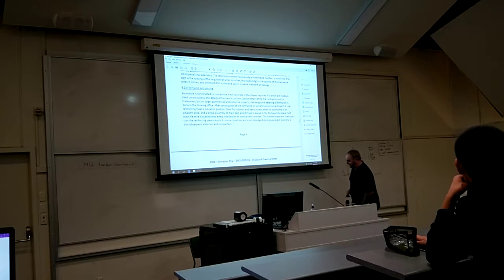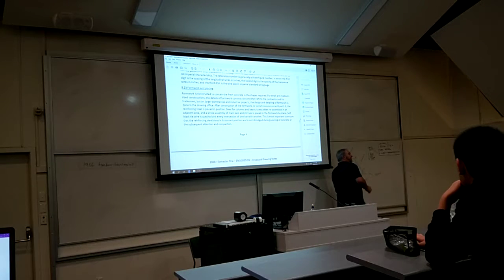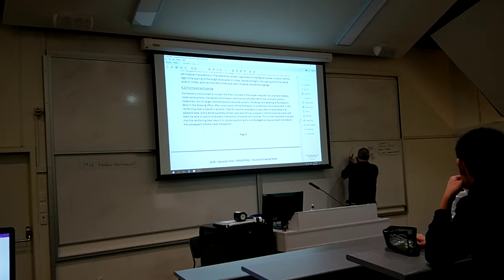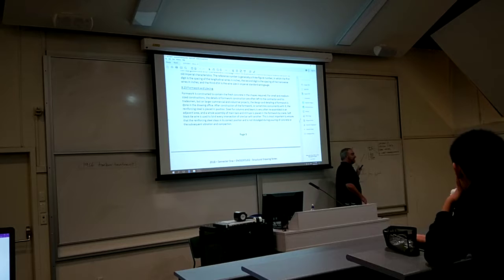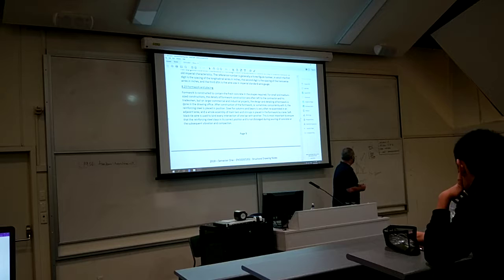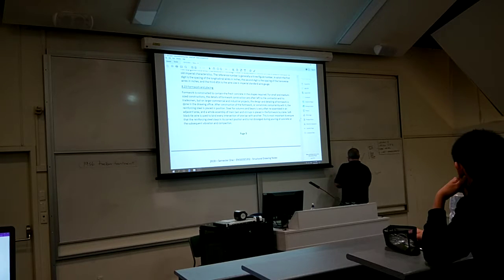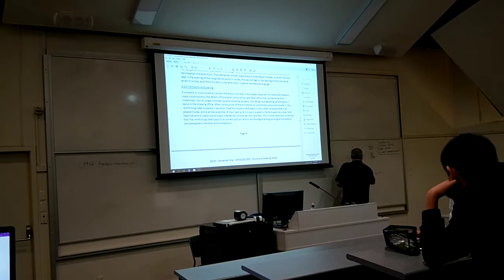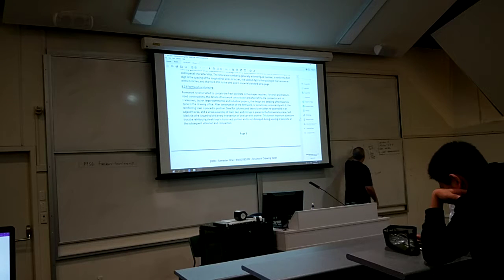So when someone says to you, go and take some measurements off the formwork, they're talking about these panels here, which preserve the natural width that you want your concrete to be, say a retaining wall. If someone talks about false work, that's what's holding that up in place. It can be done in all different ways. This is normally a peg in the ground, of course. And if someone talks about boxing, that's the whole lot.